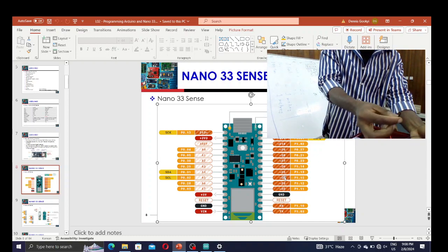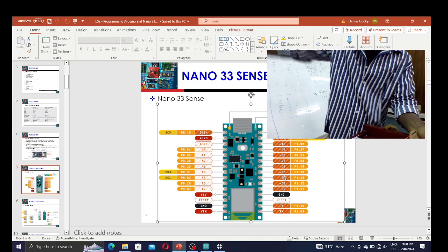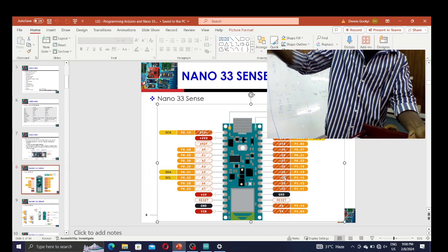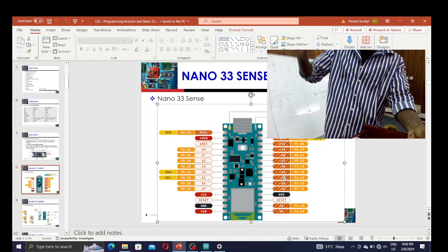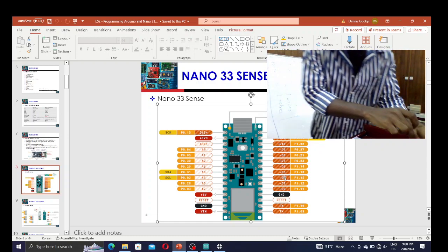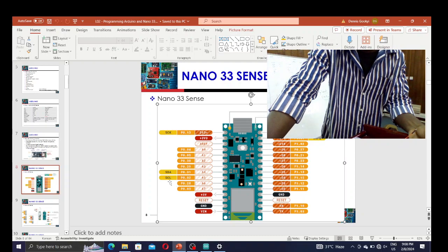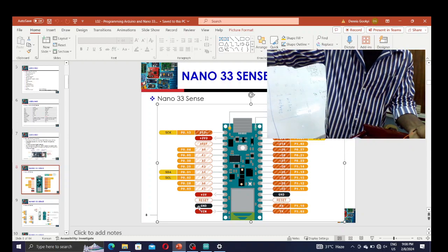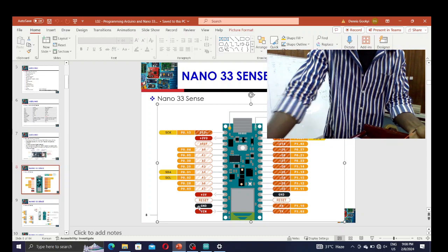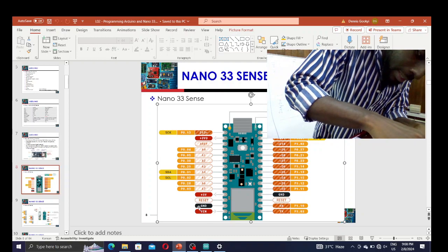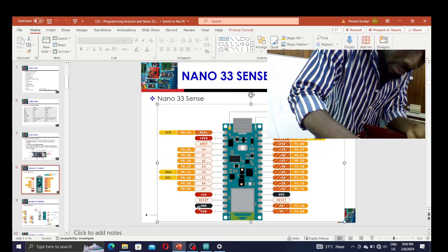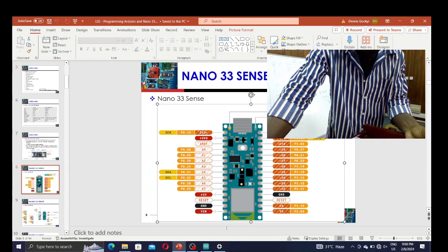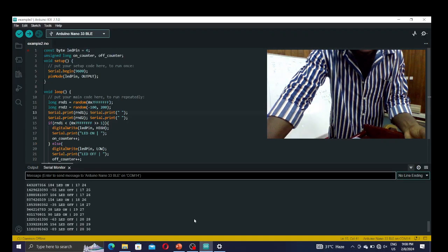I have to connect this pin somewhere. If not, it won't work. So just look at the pin mapping. I connect it to the ground. Simple. You see that the ground is here. The GND is the ground. So I connect one pin to the source, and then the ground, from the left side, is the second pin. So I just connect this one to the second pin. Right? And then I have to come and check the serial console.